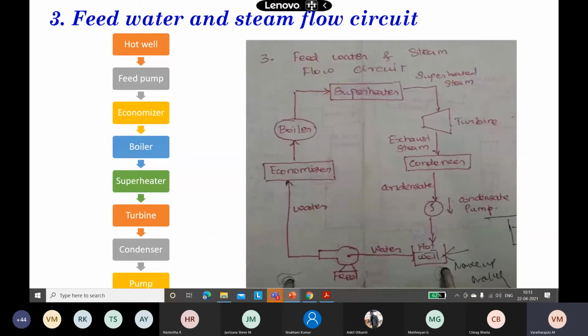the function of the steam turbine is to convert the heat energy in the steam into rotational power at the shaft on which the turbine is supported. The rotational speed of the turbine shaft is set by the frequency of the electricity supply, and is 3000 revolutions per minute, corresponding to an alternating electrical supply of 50 hertz.